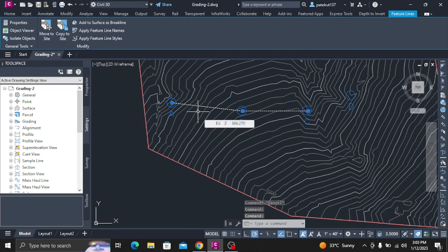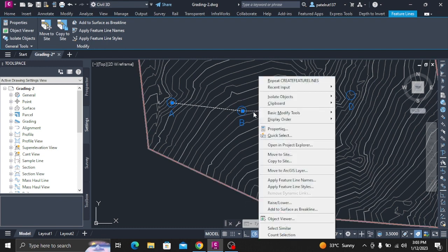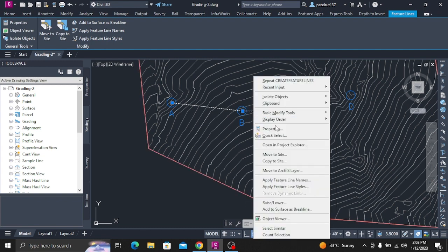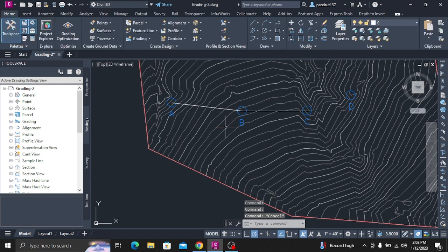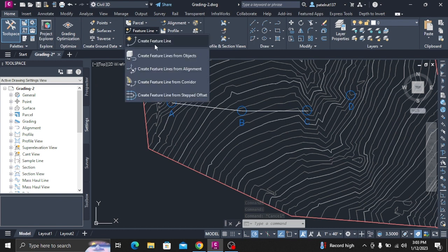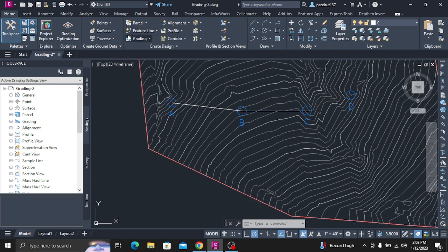When prompted for an elevation, enter T. Stretch the feature line and click inside Circle E. When prompted for an elevation, press Enter to accept transition. Stretch the feature line and click inside Circle F. When prompted for a transition, enter SU to use the elevation of the surface at that point. Note the surface elevation shown at the command line. Press Enter twice to accept the elevation and end the command.